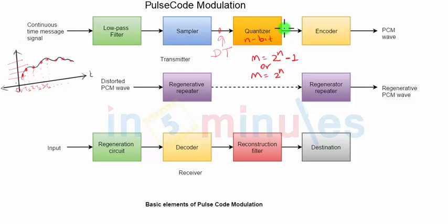The last block in the PCM transmitter is the encoder. The encoder will provide a specific encoding to the signal. The encoding process is used to translate the discrete set of sample values that we have at the output of the quantizer to a more appropriate form of signal which is best suited for transmission over a radio channel. A discrete set of values as a particular arrangement of discrete events is called a code or a symbol. So for example, in a binary code, the 2 symbols used are logic 0 and logic 1. So every discrete sample value will be represented in the form of ones and zeros.